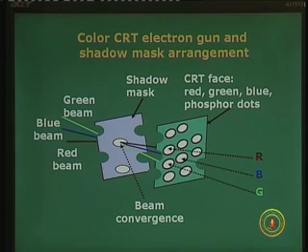They intersect, the beams converge at the perforation. This is basically a perforated sheet, like a filter is what you can imagine, but it is metallic. The shadow mask is typically metallic. A perforated sheet type of thing is what you can imagine, which has perforations or holes through which the beams are allowed to pass, not arbitrarily anywhere, and the beams converge there. Of course, nothing happens, it just emanates out in a triangular arrangement once again, and they will go and hit the corresponding red, green and blue phosphor dots on the CRT face as marked on the right hand side of the figure. The dashed arrow shows the corresponding dots on the screen as R, G and B.